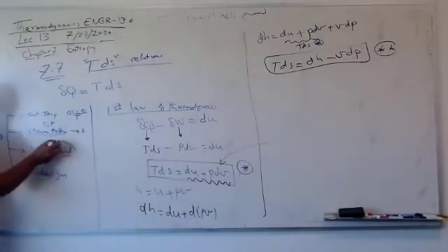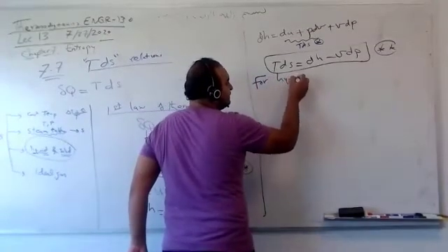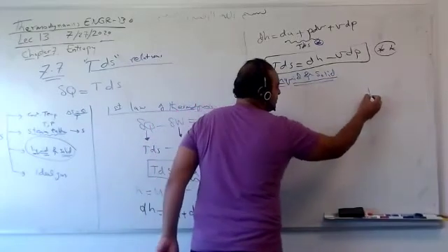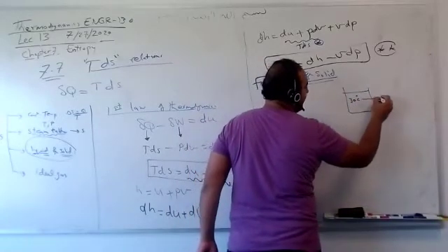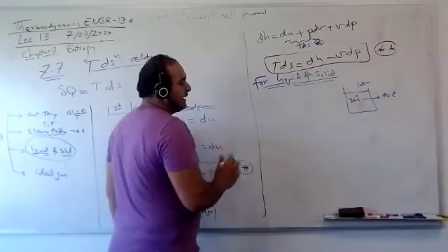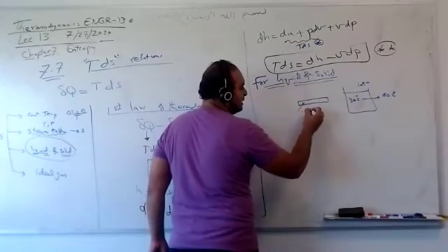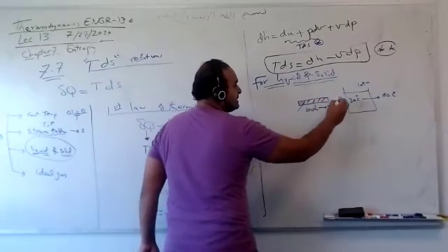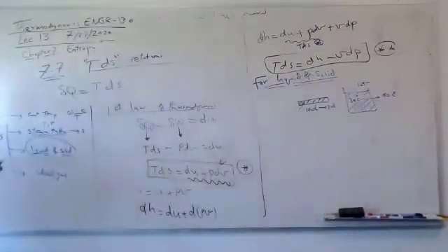Let's talk about the first special case, which is liquid and solids. Liquid means if I give you a cup of water at, for example, 30 degrees Celsius, and it became, for example, 60 Celsius, this means it remains water. If I give you a stainless steel bar, you heat it up from, let's say, 100 Celsius, or cool it down to 20 Celsius, it still remains solid. This still remains single phase liquid. If it changes phase, no, use a steam table.